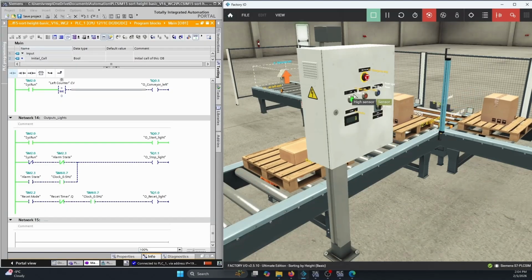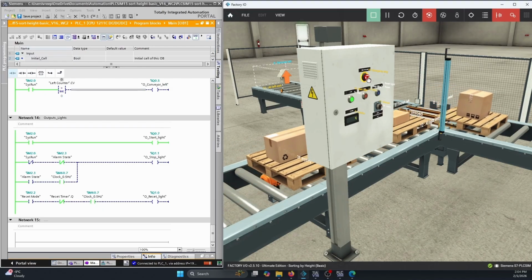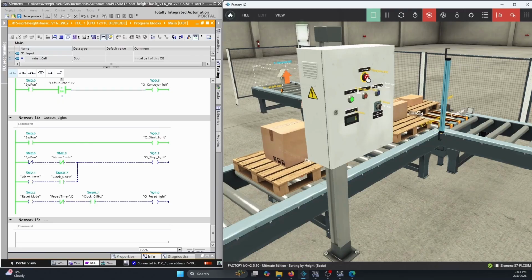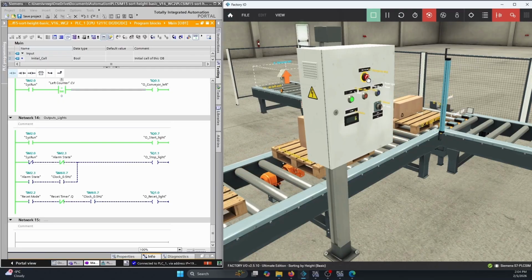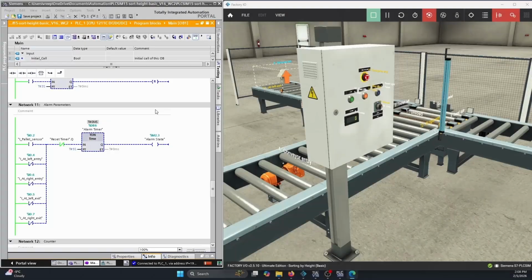Okay, next thing we're going to do is we're going to need to throw in an e-stop here, guys, because when I click this e-stop, nothing's happening in my circuit there. So when I hit the e-stop, I also want to go into the alarm state and stop all of my outputs. Okay, so we've got our emergency stop. I was thinking of maybe putting it in here with the alarm state, but this takes 5 seconds to come in, right? We want this to happen instantaneously.